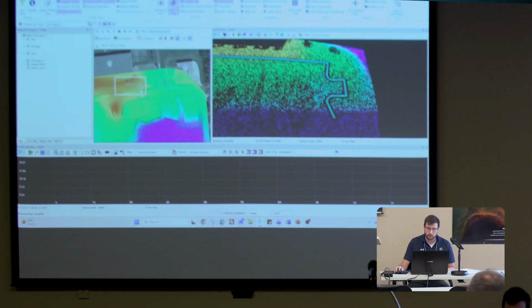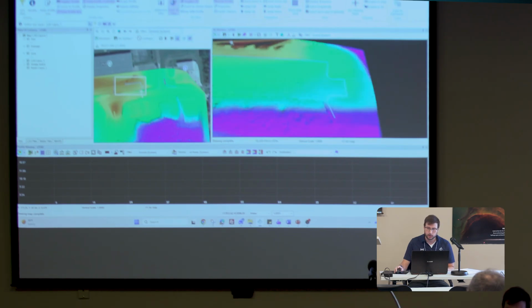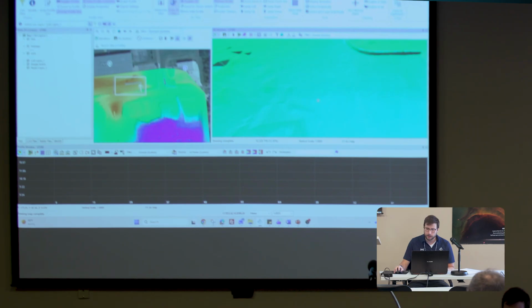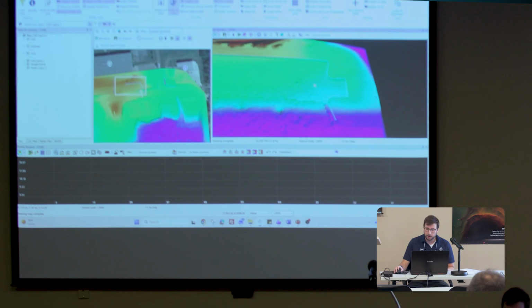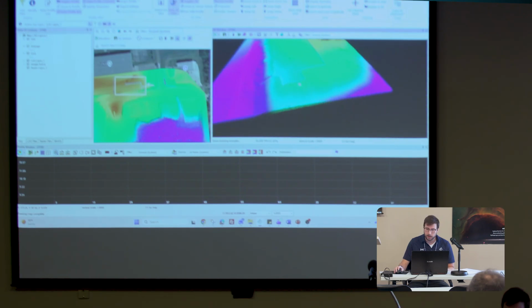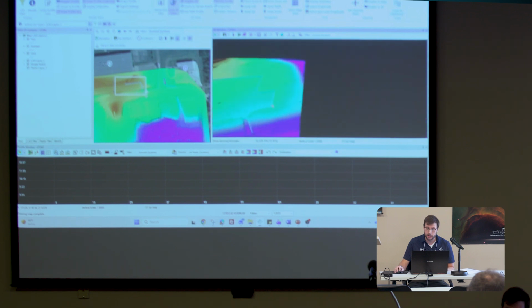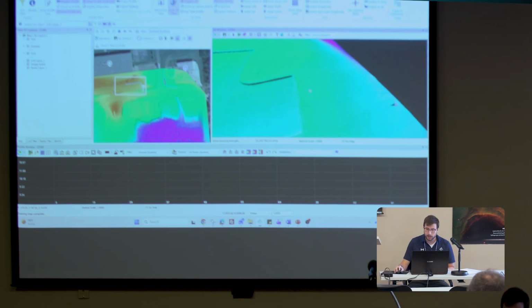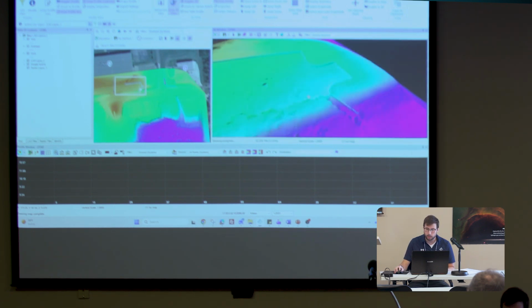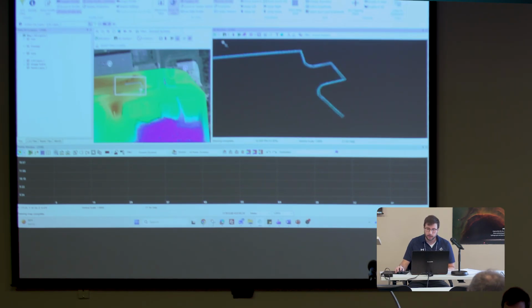Let's just see what it looks like. Of course, you have to tend the data to see what the result is. And then I'm holding down the left mouse button, moving it forwards and backwards. I can zoom in and out. Hold the right mouse button in the 3D view, I can rotate. And then both mouse buttons at the same time in the 3D view, I can pan. So I'm just glancing just to see, okay, does this breakline look like I want it to look before I do this export? I can even turn off the LAS data by clicking this legend and just make sure there's no gross errors in that shapefile we produced.